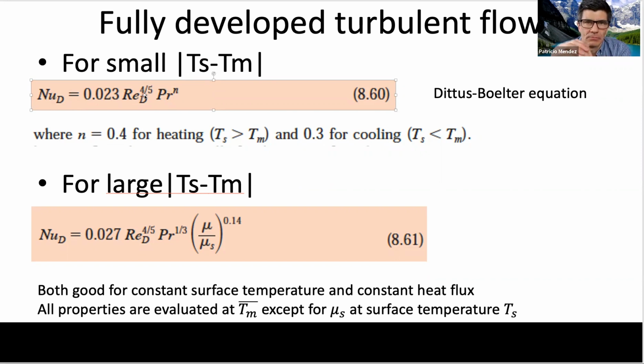A tube and an airplane wing don't look the same at all. But from the point of view of heat transfer, there is so much that is true for both. And the heat transfer by turbulence being Reynolds to the 0.8 seems to be quite universal. I cannot give you a law of why it is that universal, but I'm just bringing your attention to it because it appears all the time.